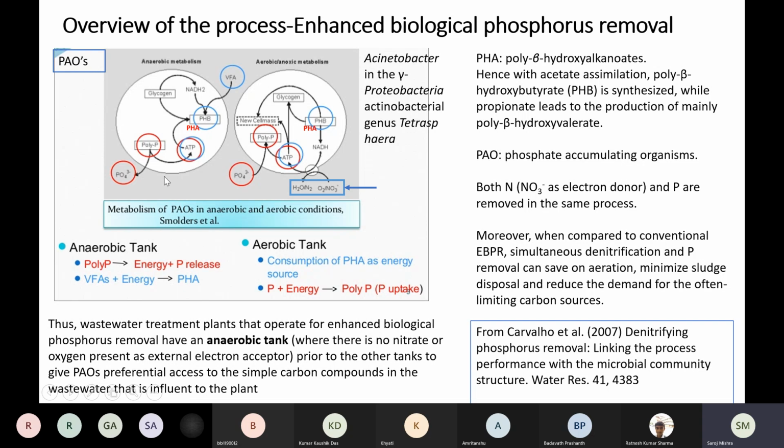In this first phase, the polyphosphates, which are a very characteristic feature of this group of microorganisms, are stored in the cytoplasm. These are broken down, and during the initial phase, the phosphorus is released into the environment. Polyphosphate degradation is also responsible for ATP generation. This ATP is used to synthesize PHA. So that is the anaerobic leg.